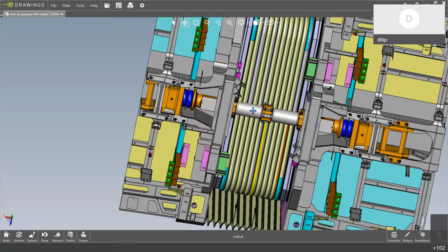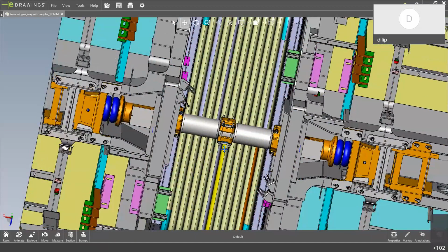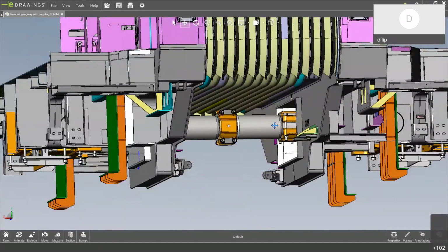The main difference is, if you see here, the two shanks, these two tubes, and this is a muff coupling. Whereas in a CBC, you will have a knuckle arrangement. In this, one knuckle will come here, another knuckle will come here. Instead of the knuckle arrangement, we have a muff coupling. This muff coupling is fastened by fasteners. Here, if you can see, there are 1, 2, 3, 4 sets of fasteners. So the muff coupling used here is used here also.